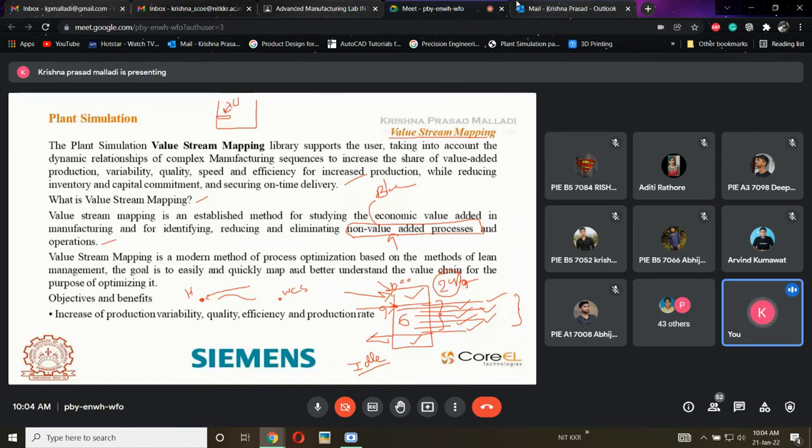But my WCS would be like my bed will be at the center of the table and my tool is supposed to be at a height so that the part will be fixed instantly. So this is my WCS. WCS is a position where we are going to start our work. Home is the position where the machine will stop, or where it will start from the initial run.